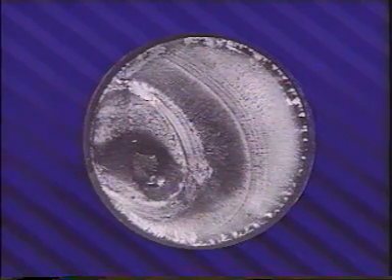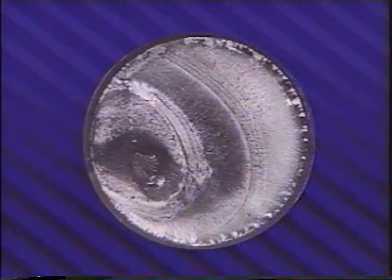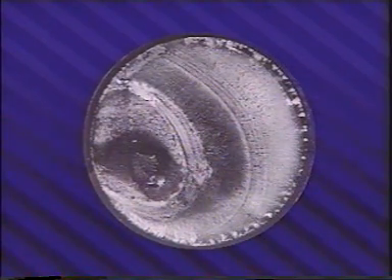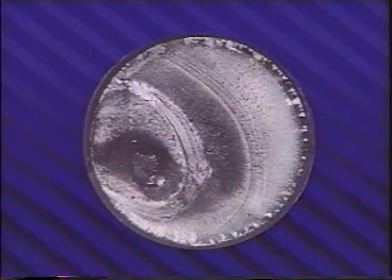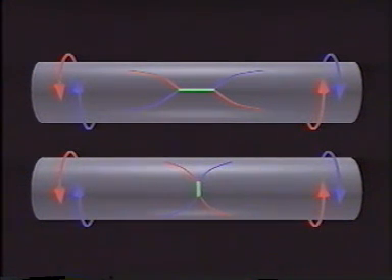Investigation revealed that the rotating bending force on the output spline was unbalanced. This caused maximum bending stress on the right side. Here, the fracture origins are evident. Consider torsional loading. Under torsional loading, the maximum local tensile stresses are at 45 degrees to the axis of the shaft. Under a fluctuating torsional load, fatigue cracks will develop perpendicular to the tensile stresses.